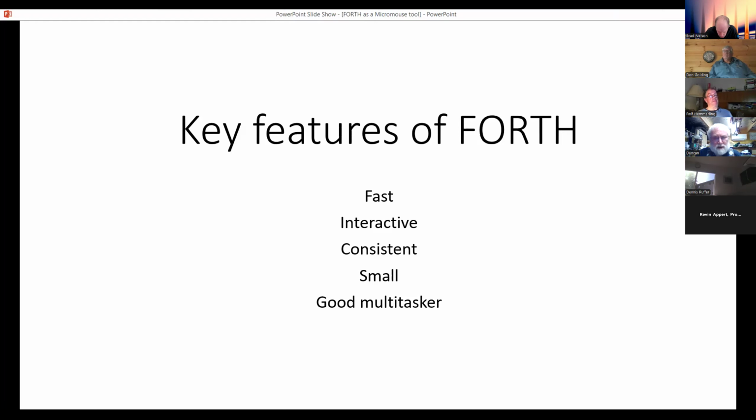Multitasking is pretty much ideal for Micromouse. Because of the real time constraints, any preemptive scheduler will introduce jitter into the control loops, so a cooperative one is better. Tasks don't relinquish control until they're good and ready, so task swaps in critical code don't happen. Typically, I'll have a control loop task that runs to completion without any pauses.